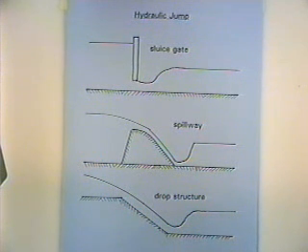I'll not flip back in the notes, but on the diagram you notice when the specific energy is a minimum, we've got sort of a curved surface where there's a very significant change in depth for a relatively small change in energy. The water surface will jump up and down when you get near critical flow. And that's what's happening with a hydraulic jump. It's really jumping up very abruptly.